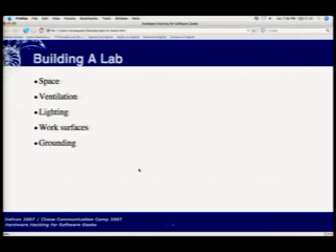In addition to the space, it's also very important how you set up the space. If you have a table like this one here, you're not going to want to put any electronics on it, because this is a tablecloth. And as I'm sure half of you in here have heard of ESD, electrostatic discharge. You won't know if ESD has damaged your device unless you hit the lottery, and basically it makes it not work at all.